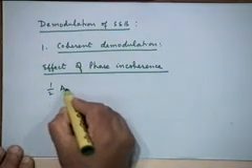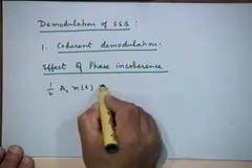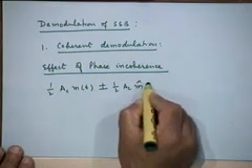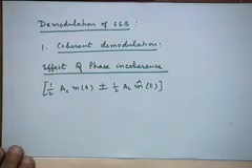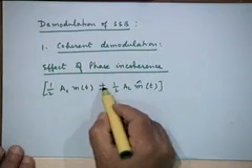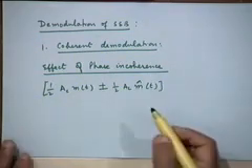We know that I can represent the SSB waveform like this. This is the expression for the SSB waveform with a plus sign for the lower sideband and a minus sign if I want the upper sideband. So either of these two is fine.